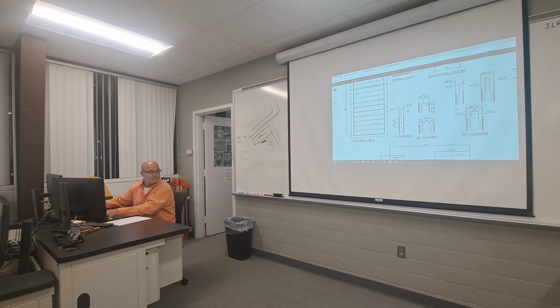In this area, you will see all of your parking scenarios. If you have some parallel parking, there's your design for that. They need a minimum of 20'6" curb to curb if you've got curbs there. If not, still need to allot for that much space for those parking. The parking spaces are 8'6" wide, 24 foot long. And you need at least 12 foot to be able to parallel park into those spaces next to it.